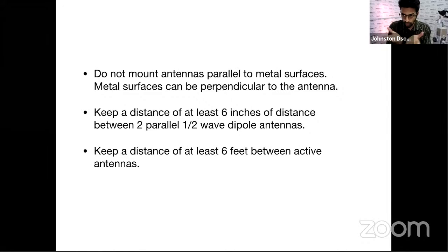That's the reason why with Wi-Fi systems, you keep the antennas at least about 5 to 6 inches apart from each other. That's the reason it's made in a V shape and not kept parallel. So if you have one of these massive routers which have 4 antennas on them, make sure that the antennas are about 5 to 6 inches apart from each other.